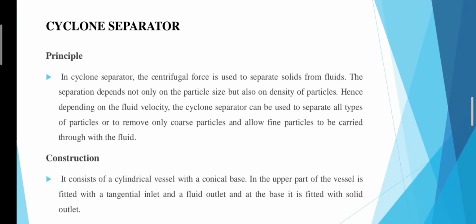Next, second, cyclone separator. Principle: in the cyclone separator, centrifugal force is used to separate solids from fluids. The separation depends not only on the particle size but also on the density of particles. Hence, depending on the fluid velocity, the cyclone separator can be used to separate all types of particles or to remove only coarse particles and allow fine particles to be carried through with the fluid. Cyclone means wind. In the cyclone separator, the mechanism is centrifugal force.